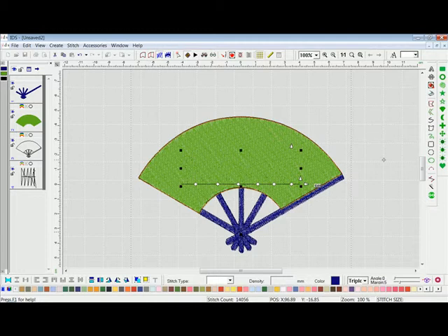outline is now highlighted in red. I then have to make a second point for my other endpoint, left click, and as I do that, I can move my cursor over the top and it will turn blue, or the bottom and it will turn blue. So I have two possible text paths that I can choose from. I want to choose the top text path, so as soon as my cursor is over that text path and it is blue, I will left click to set. Now you can see my lettering will fit exactly on that existing outline.